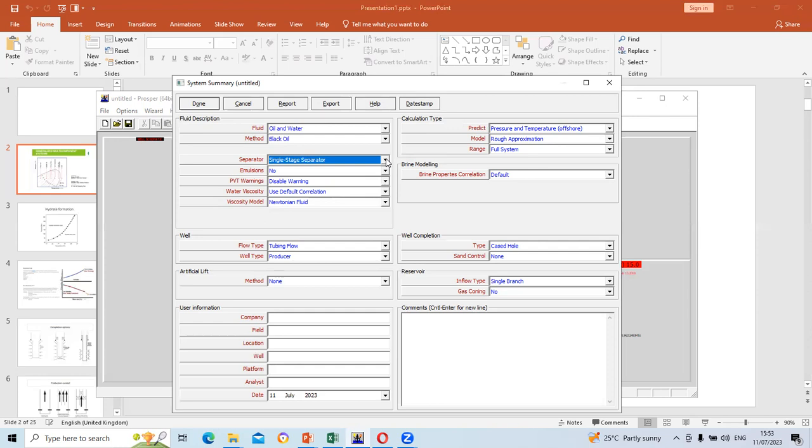You have water going its way, we have oil going its way, and then we have gas going its way based on their gravity, because water will generally settle at the bottom. So there is a tube at the bottom that helps to drain the water. There's another tube connected at the central part that drains the oil. And then there's another tube connected at the top part where the gas can easily flow. This gas is the lightest.